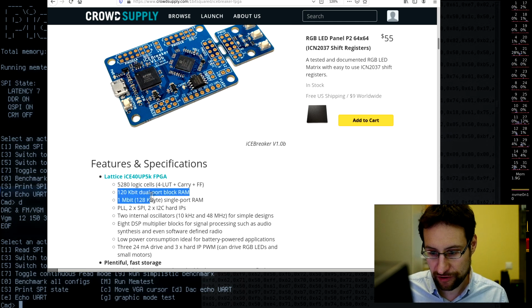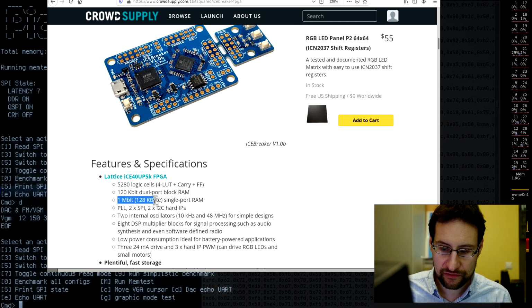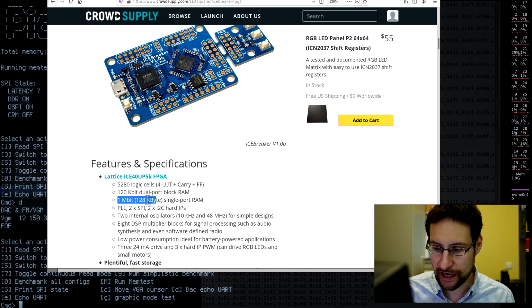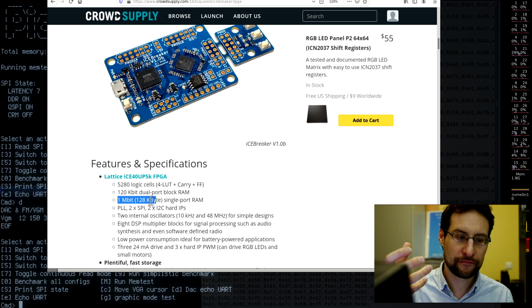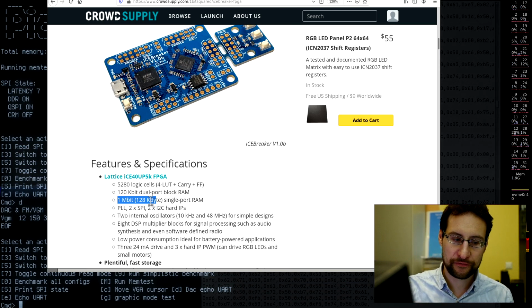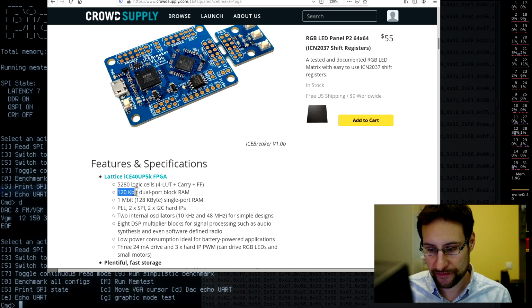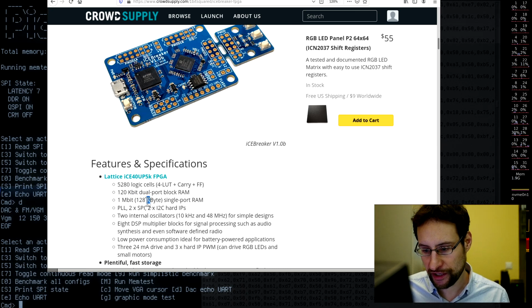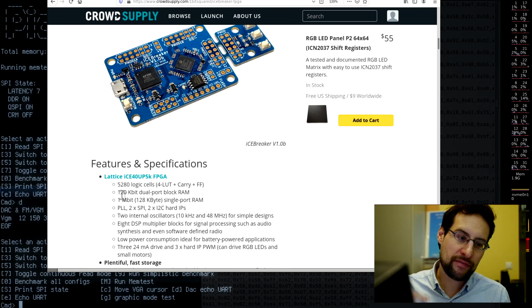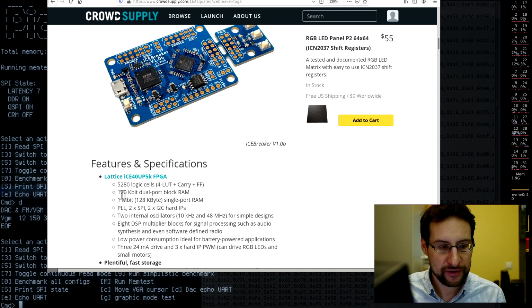Unfortunately, we don't really have that memory unless we would sacrifice quite a bit of the system memory of the RISC-V. So we could halve this, but I would rather have 128K for the RISC-V software and somehow live with a smaller frame buffer. We could theoretically make this 32K. Maybe eventually we work with larger FPGAs sooner or later.